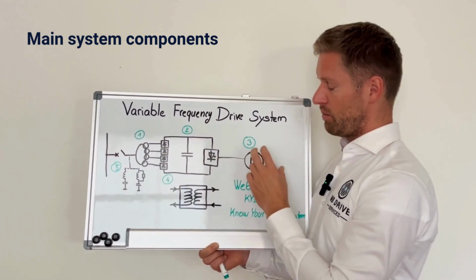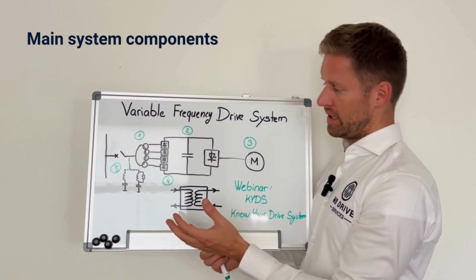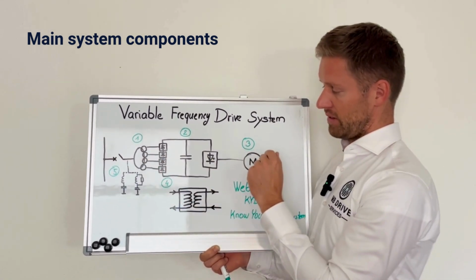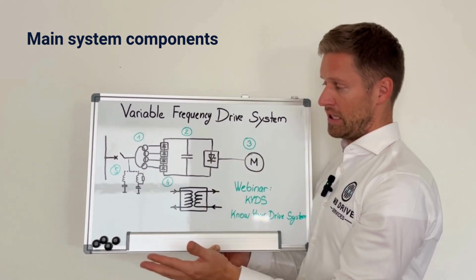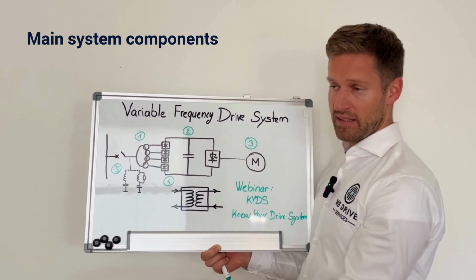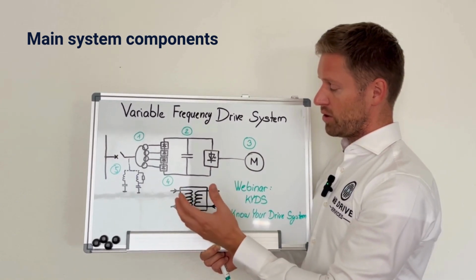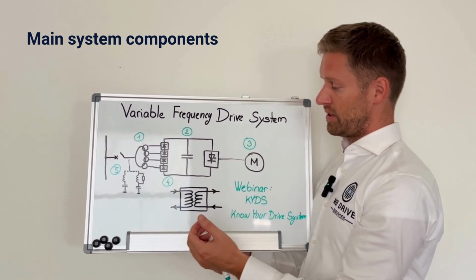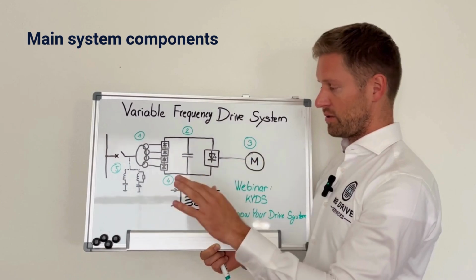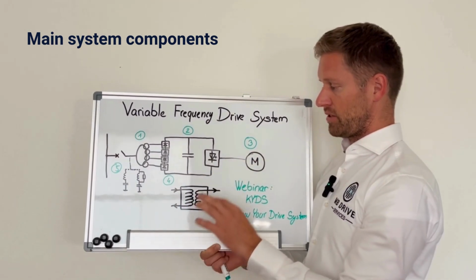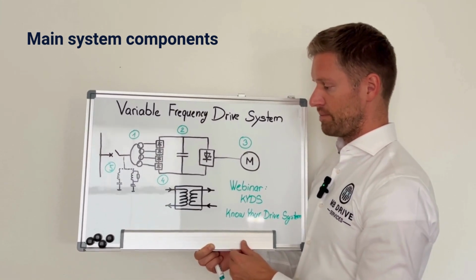Each of the system components has certain losses that are dissipated, and although they have generally very high efficiency, we can talk about nominal efficiency in the range 97 to 99%. It's still a certain amount of power losses that need to be evacuated from the source in order to maintain a stable temperature and guarantee the proper functionality and lifetime.